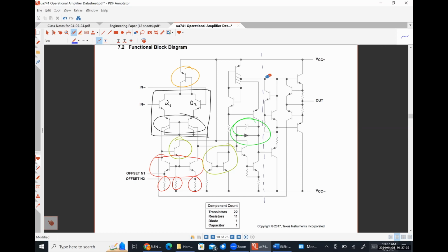Okay. Now, what we did today explicitly was figure out what happens when we don't have the ideal case, right? So what happens when we are making a real op-amp, and our transistors aren't perfectly matched because some misalignment happened in our fabrication process, either misalignment in the size of the resistors or in the size of the transistors, and how that manifests in affecting the overall voltages. Did that maybe kind of clarify what we're doing?